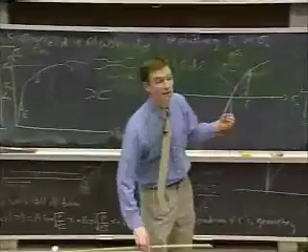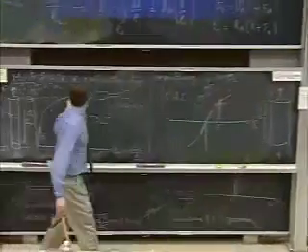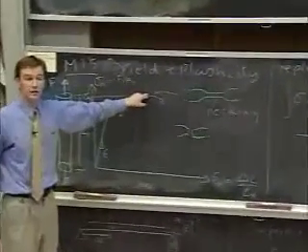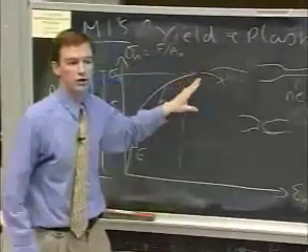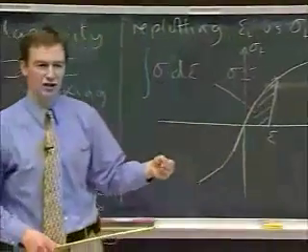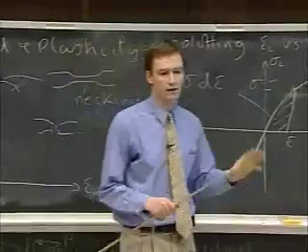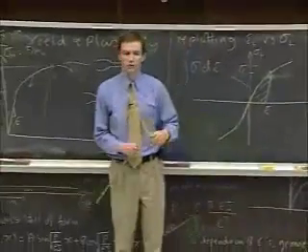That's a failure stress. So for a metal, it's usually the ultimate tensile strength, this number. For a ceramic or a brittle material, it's the strength at which fast fracture occurs, and we'll understand that distinction a little bit in about 3 lectures' time.